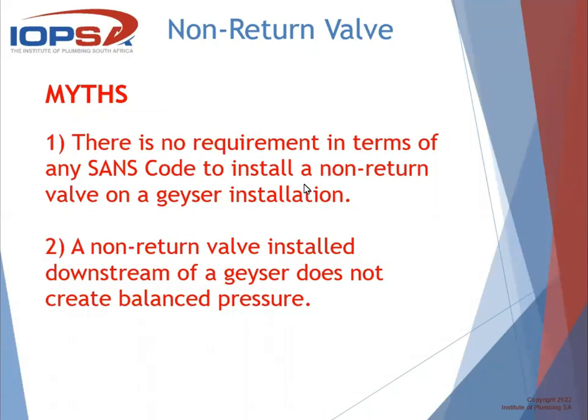Yeah, if I recall correctly, I actually read it yesterday, in 10252, they talk about this regarding pumps, and also your anti-siphon loop on the solar systems, where if your flow rate is not strong enough, you're going to have problems there. So you have to have a look at your pressure rates and your flow rates before you install this, to make sure that you're not creating a problem instead of solving the issue.